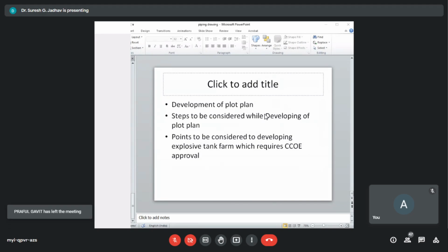Study the contour map and establish the grade levels and terrace. Then establish north, south, east, west on XY grids. Plan north in relation to geographical north. Establish the free area along the plot boundary as per the statutory norms. Work out the area requirements for the green belts and vehicle parking as per the norms.